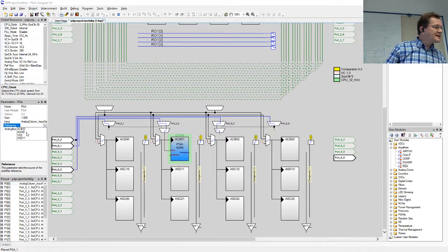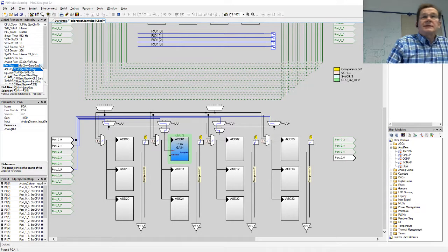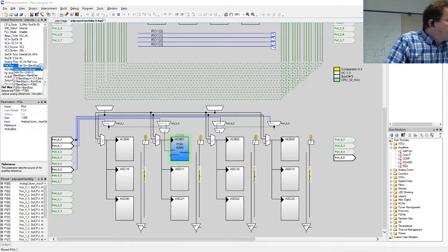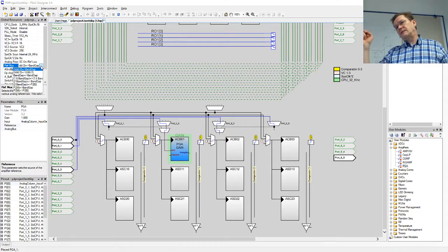And the global settings are right here. It basically gives you the reference multiplexer. So that's the internal reference for signals. To have any accurate results from A to D conversion without depending on the operating system voltage level, then you need to reference everything on the band gap.